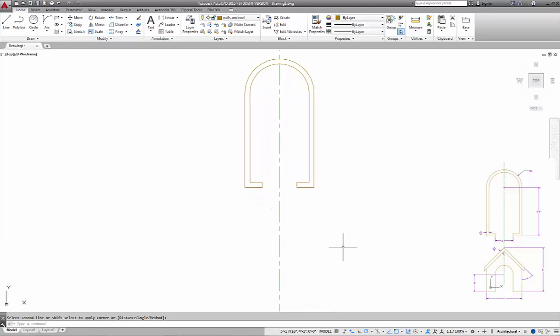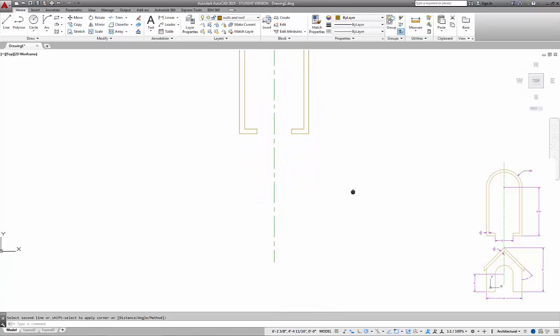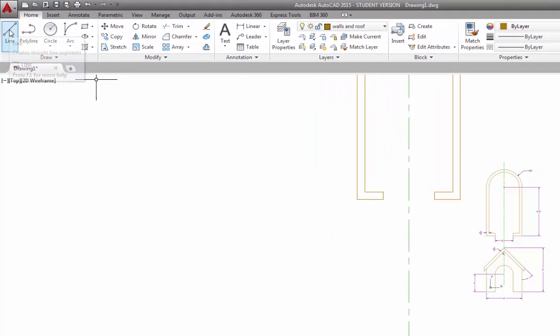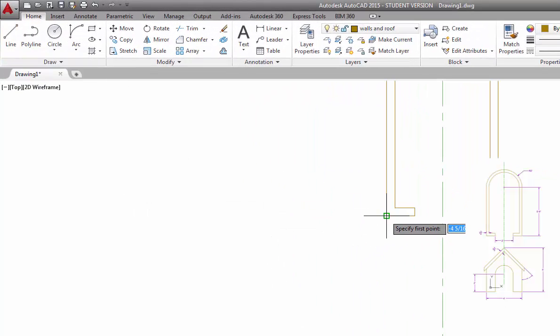Well, that's the top half of the doghouse. The bottom half, or the front view of the doghouse, begins down here. So to create the bottom half of the doghouse, we'll need to project the doghouse down. We take the corner and highlight it, don't left mouse click, just highlight it, and notice that we get an extension line. Remember that object snap called extension? That's what we're using here. So we're going to pick a point down here.